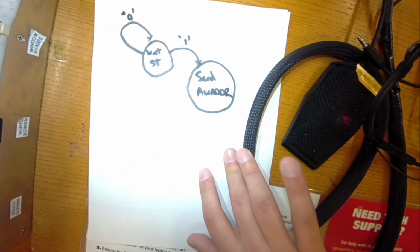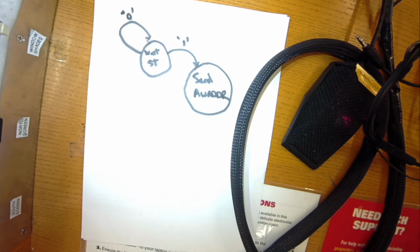Now, I do like to separate the concept of what we're doing in a state machine from the implementation, but just a small word of advice that the 2 process state machines tend to work pretty well in terms of how to implement these things and get the results that you generally expect. That would be one process that's reacted to the clock, that's a synchronous process that checks current state as well as inputs and determines when we should go to the next state.